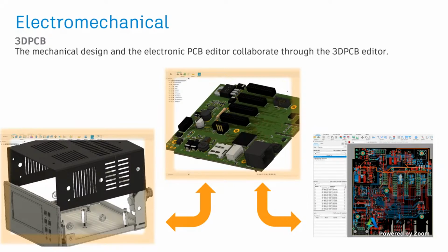And we have the capability, if you've been using or looking at Fusion at all, called edit in place. I could actually make changes to component placement on the design workspace, and that actually annotates back to the 3D PCB, which in turn will go back all the way to the circuit board. So as you could see, all the latest changes are always adopted by the 3D PCB. It's really important that you understand this workflow.